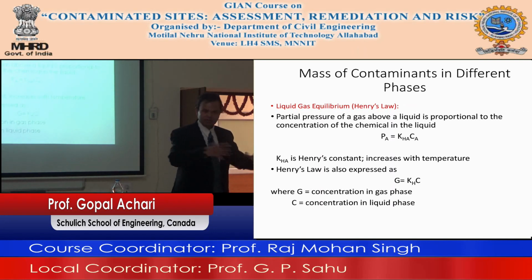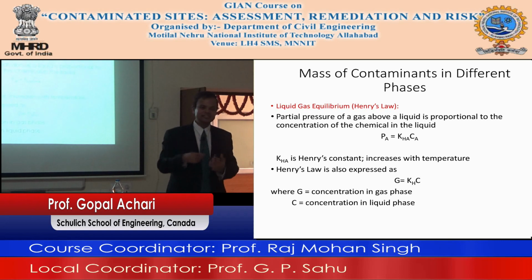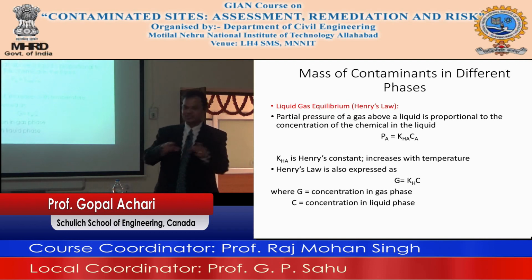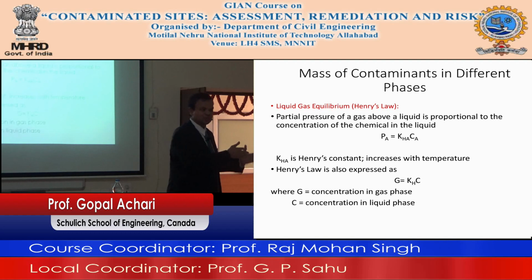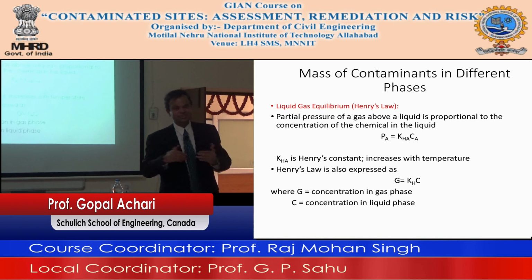Let's say you have a gasoline contaminated site, and you pump the air out. Once you pump the air out, all the gasoline that is in the air phase will go, but the gasoline from the dissolved phase or the adsorbed phase will now start to get into the air phase, and the equilibrium will shift. Now you will have a continued phenomenon in soil vapor extraction, which we will learn, I don't know, tomorrow or day after, whatever. You will see what is known as a tail effect, and the tail effect will completely blind you.